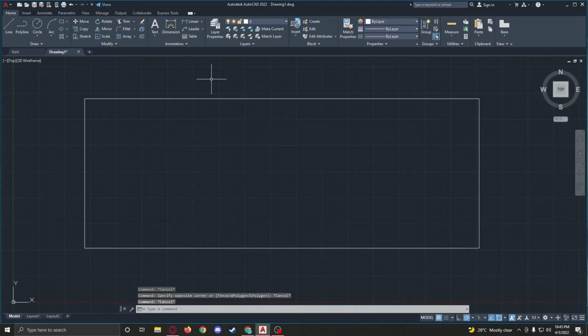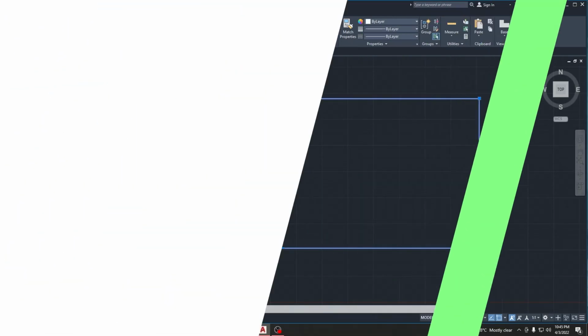With that, you can draw a window or individually click on those objects or lines. When you're done selecting the objects to join, press enter and it joins them back into a polyline. So that's it for the explode command along with the join command.